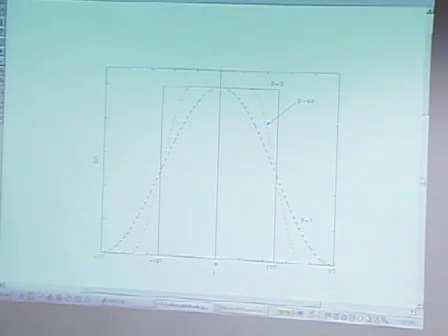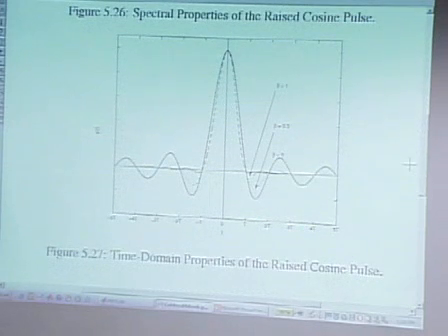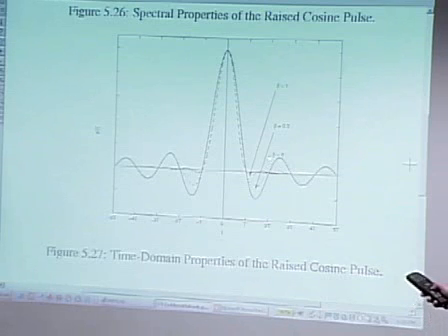So let's look at the answer. As always happens in Fourier transformation, there is duality. Let's go to the other domain, the time domain. What happens when beta is smaller? Yes, you have a larger cycle, exactly. So what's the consequence of this? We said that the crossing points are 0, and that remains true. For any beta, you always have 0 at the multiples of T. But the cycles in between grow larger.